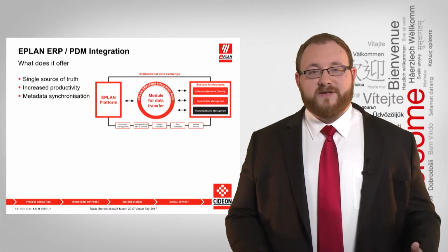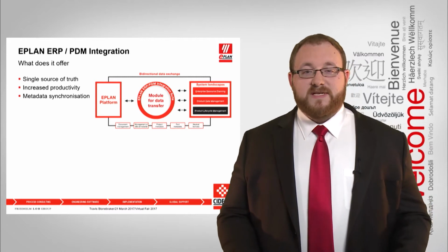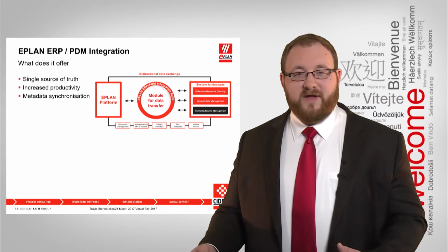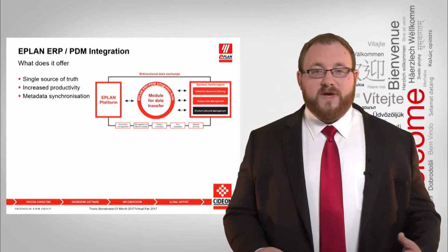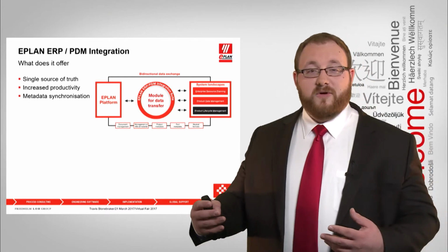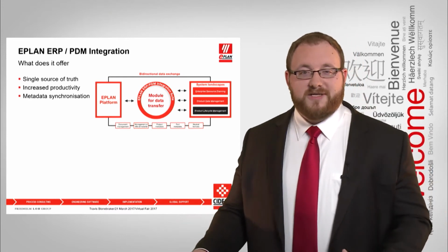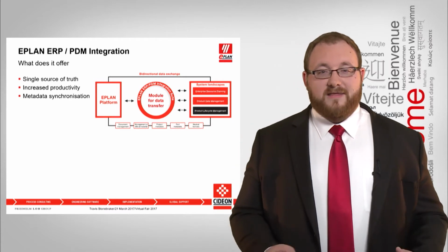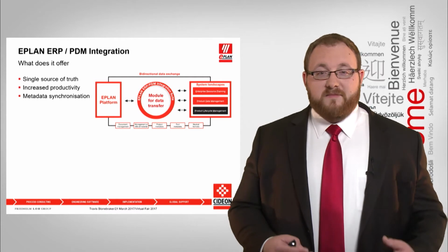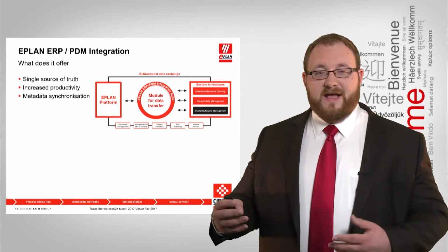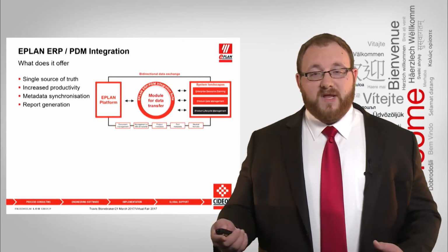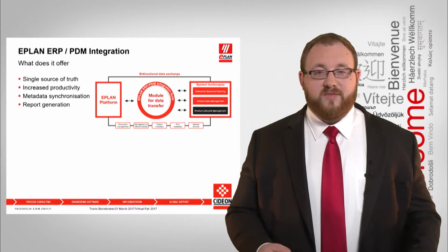With metadata synchronization. For instance, you can take information from your PDM system and put it on the project level of your Eplan project, or you can take certain information from your ERP system and migrate it to your parts database within your Eplan project. This could mean anything from a description within a document or a customer name, customer logos, as well as any kind of part information, as well as the ERP number that is within the actual parts library.